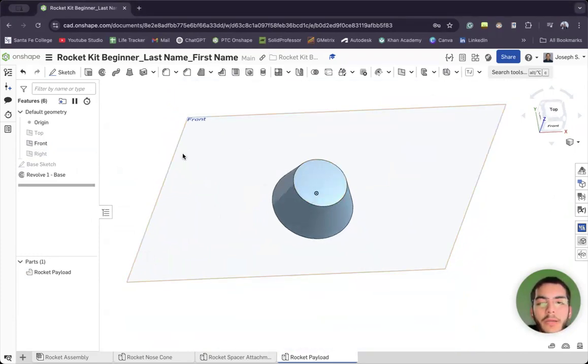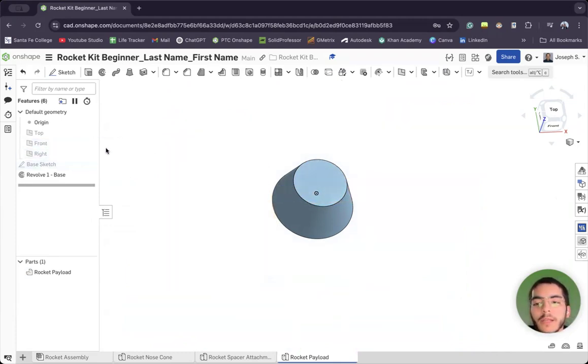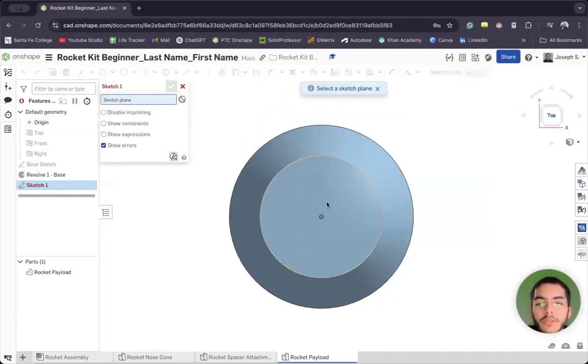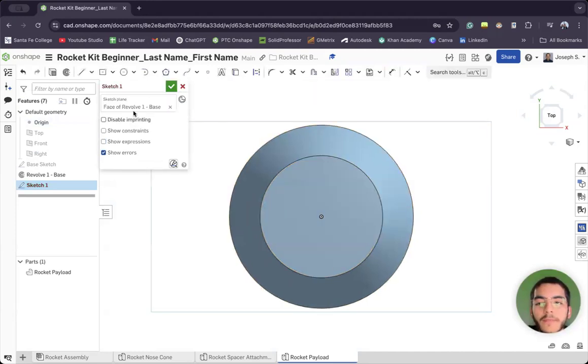Once we do that, we'll create a new sketch on the top plane here. You could go ahead and hide the front plane if you want. So click the eyes here to hide it. Maybe like you see this cross line here. Then we're going to click the top plane on the view cube, click sketch, and click the circle here. There you go. And we're going to hit center point rectangle again, or R on our keyboard, and hit the midpoint of the circle. So it's going to be this. We're going to pan out and click once and it completes the shape.